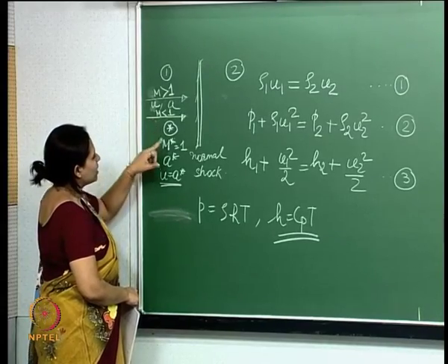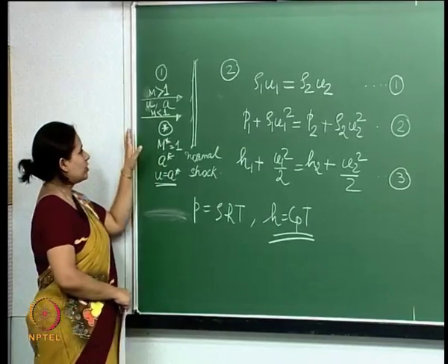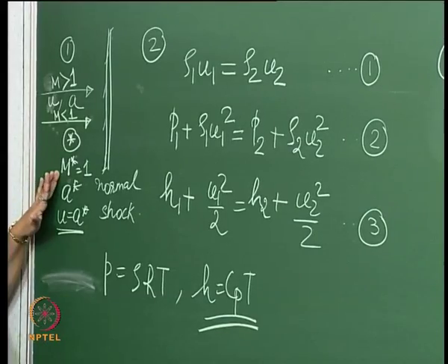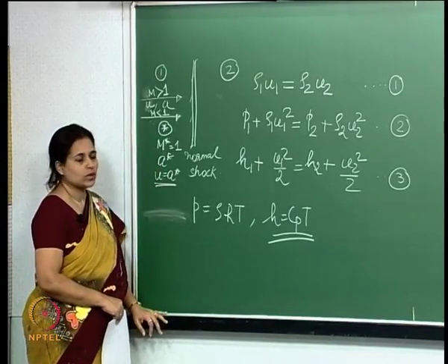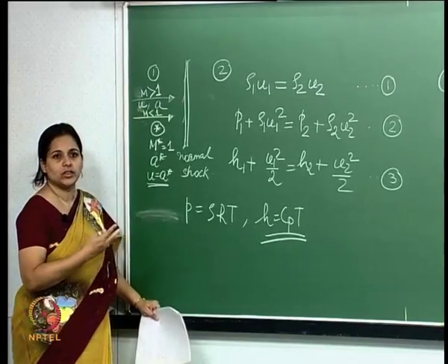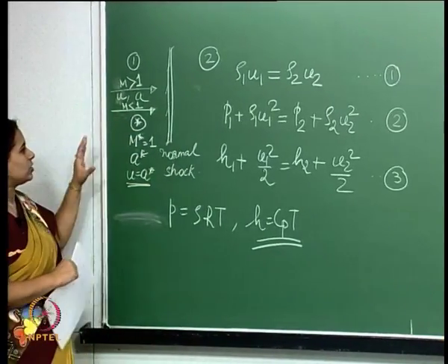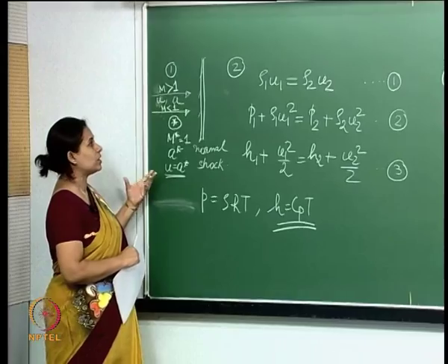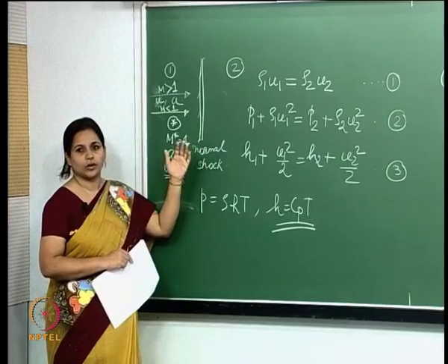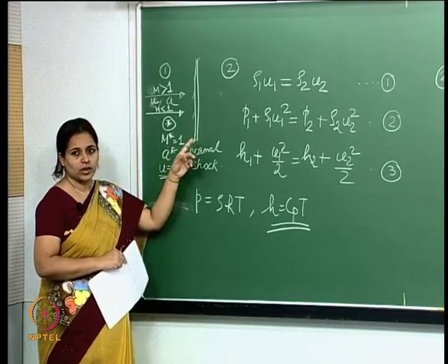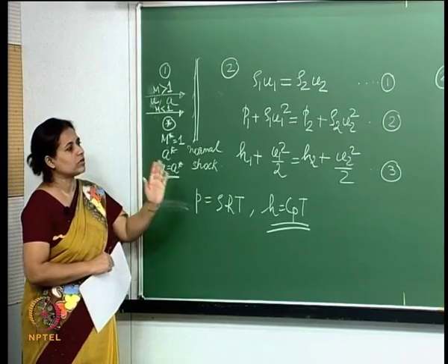In this case, we will again reach this sonic point by speeding up the flow. So, we speed up the flow so that it becomes sonic, and the corresponding speed of sound here is a star. And we will see the usefulness of this as we introduce it into our equation. What we are not able to assume here is what exactly is the incoming Mach number, or the speed of the flow which will actually cause a shock wave. We do not know that; we will do all these studies and then try to get an answer for that.